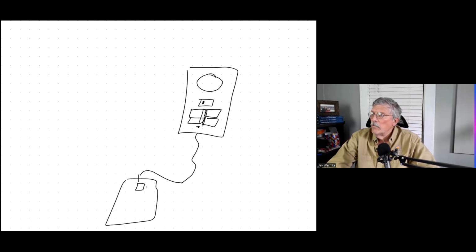So you're just going to get a new meter box. You're going to have to turn off your service. They're going to install this thing, and then there's going to be four empty breakers right here. Well, that's an awfully nice place to hook in. This is my AC disconnect. This is my inverter. Then I can hook right in here, and I don't have to be drilling holes in the wall to get to my service panel. I can just hook into the empty port out here at the meter.